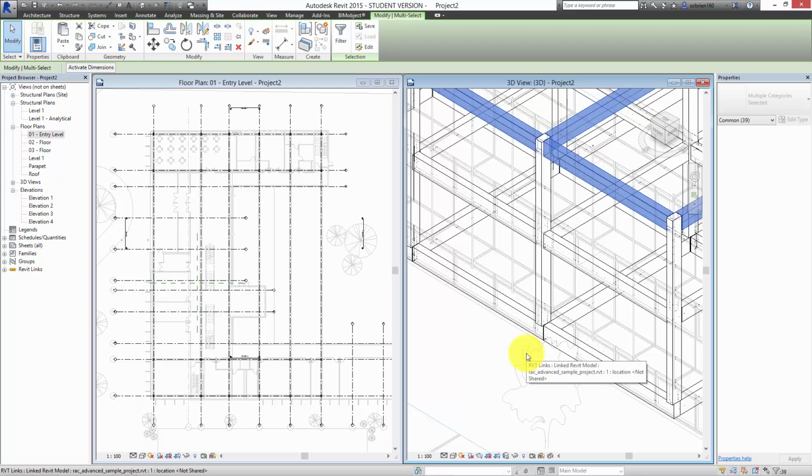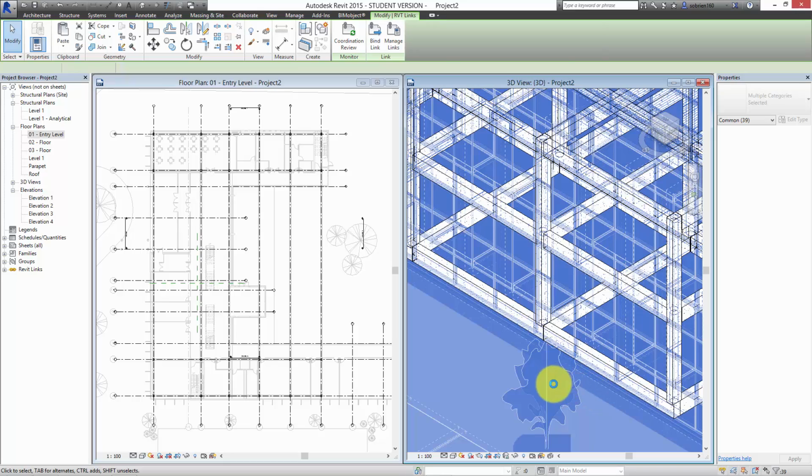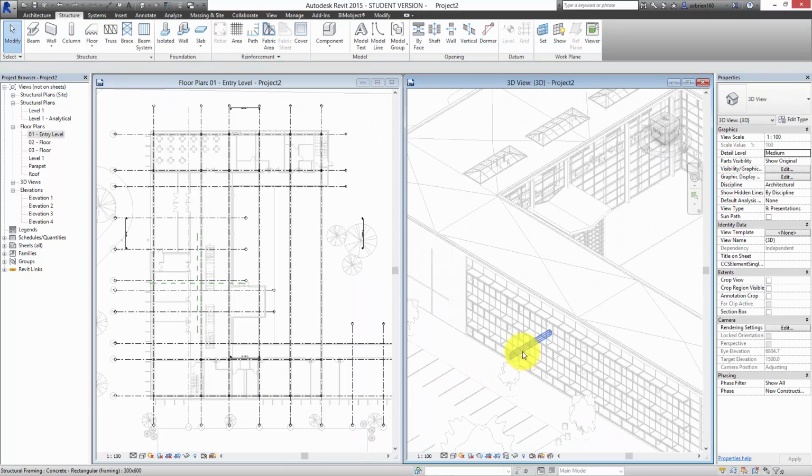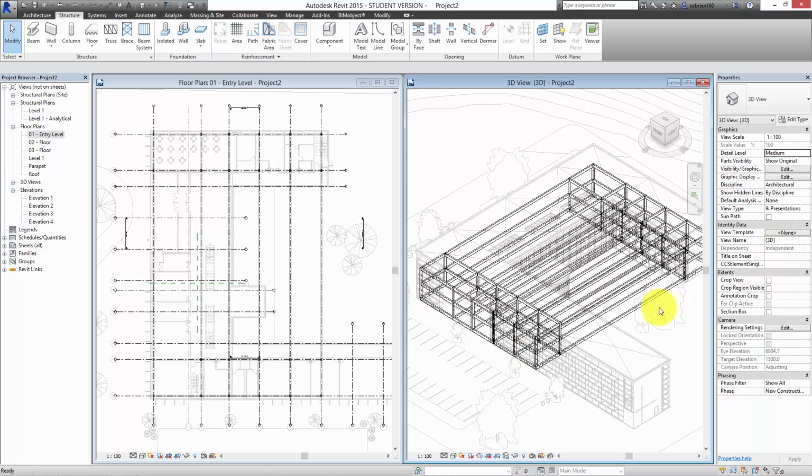Let's just try and zoom out a bit. You can see that this is slowing down a little bit. Now we've probably gone a little bit too much to town here on the position of them. Got too many of them, but we can always just go in afterwards. Once Revit has automatically placed them, we can just go back and delete them afterwards. So you don't have to really worry about placing them directly. You can just do it very quickly over the entire grid section, and then just delete the ones you don't need afterwards. It just makes it more efficient and easier to work that way.